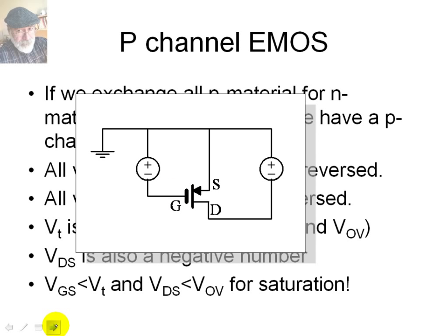Now the values. I'm telling you that this source is 3 volts like that, and this is -7 volts, and the transistor is specified by this conductance value and this threshold voltage, -1, because this is a PMOS. My question to you is, what is the mode of operation of that PMOS?